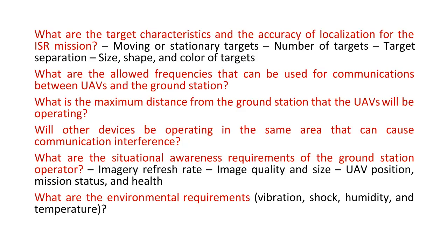What are the situational awareness requirements of the ground station operator? Imagery refresh rate, image quality and size, UAV position, mission status, and health. What are the environmental requirements: vibration, shock, humidity, and temperature?